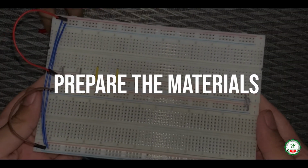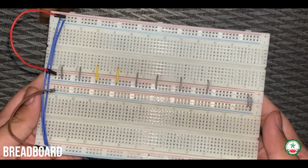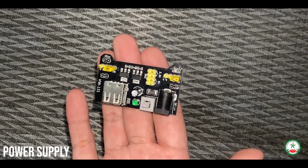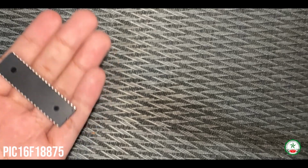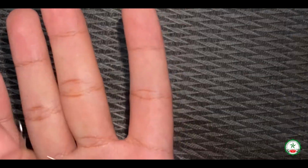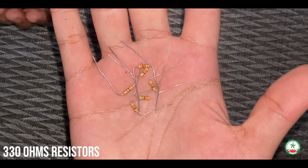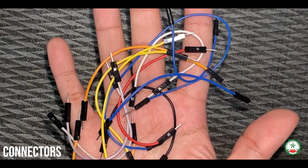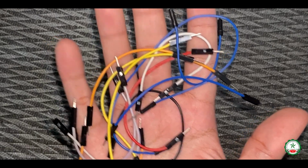So prepare the materials needed. So first, the 2 breadboards, a power supply, the PIC16F18875 microcontroller, 8 330 ohms resistors, 8 LED lights, and male-to-male connecting wires to connect the components together.